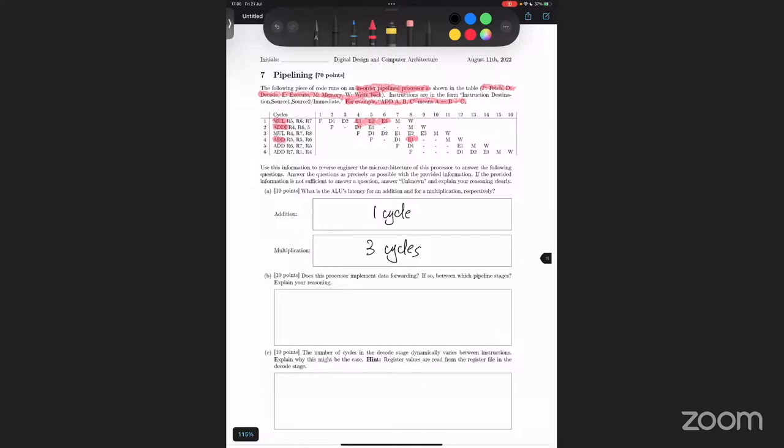So we should look at the later half of the pipeline to see whether some data-dependent instructions have already resumed execution before the input data is written back. The first step is to find the instructions that have data dependencies.